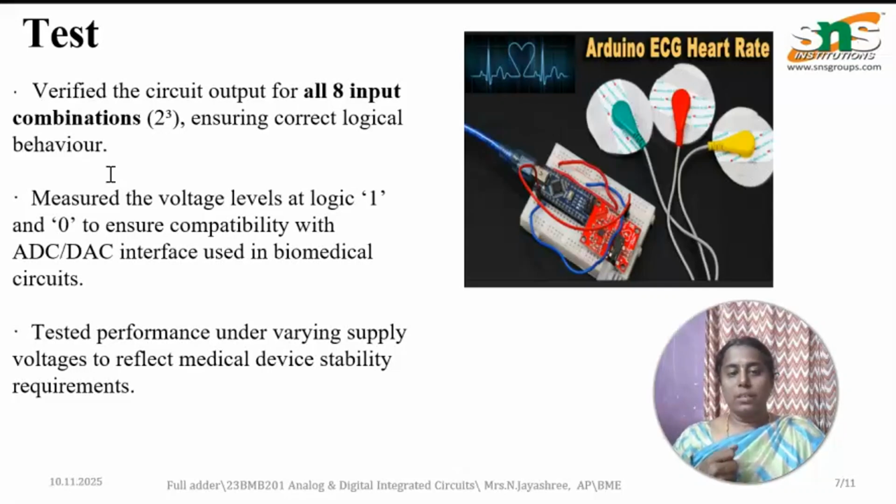It also measures the voltage levels at logic 1 and logic 0 to ensure compatibility with the ADC and DAC interfaces used in biomedical circuits. Test performance under varying supply voltage to reflect medical device stability and requirements.